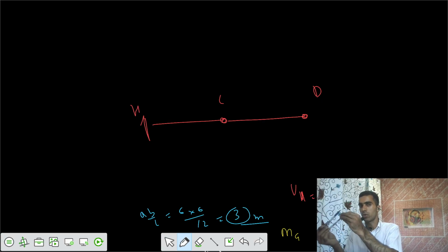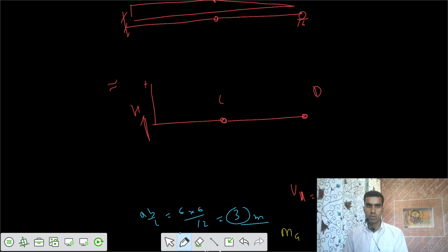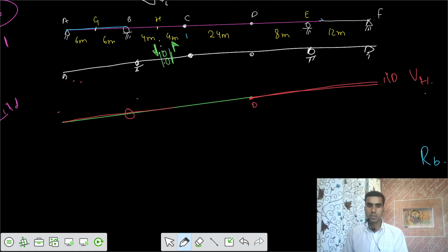And from this side, it won't go anywhere. That is a proper cantilever from the other side. So it is similar to, I can show, this is your cantilever with some internal hinge. After that, you have a cantilever, and you want to say, what is the reaction for A? I would say reaction at A is in this fashion. Similarly for this one, if it goes upwards by 1 unit, because we know that V1 equals 0, so V2 equals 1 unit. If this goes 1 unit upwards, after that it would remain straight. Then to maintain that intact condition of D, we say this is your variation. So finally for this part, we have this variation.